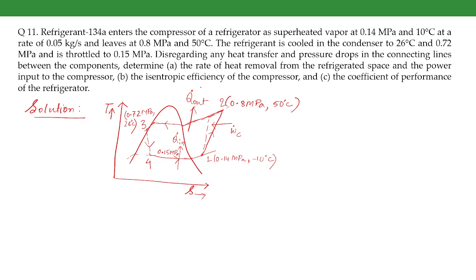Okay, and this point is the point corresponding to the isentropic compression. Now from 0.8 megapascal, as the refrigerant is flowing through the condenser tube, it again undergoes a pressure drop, and the pressure drop is more here, like it is 0.08 MPa, that is 80 kilopascal here. Okay, in the condenser.